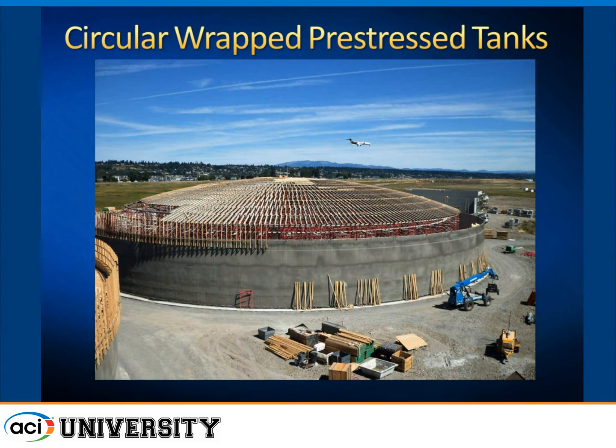Dome shells are specifically covered in 350. And these walls may be cast walls. They typically are pre-stressed either vertically or with a steel shell inside. And this one has a significant amount of Shotcrete that's used to make up part of that wall.